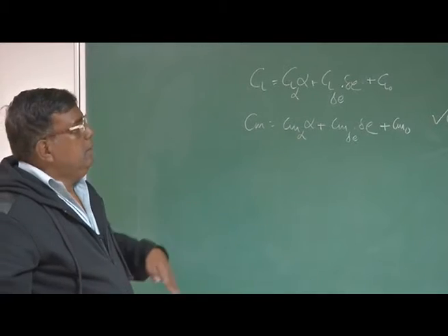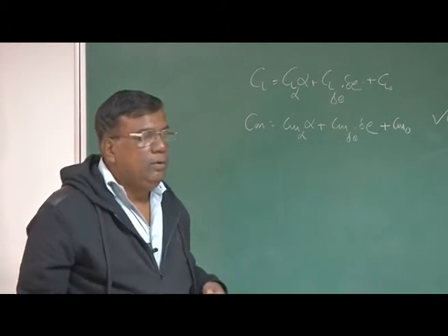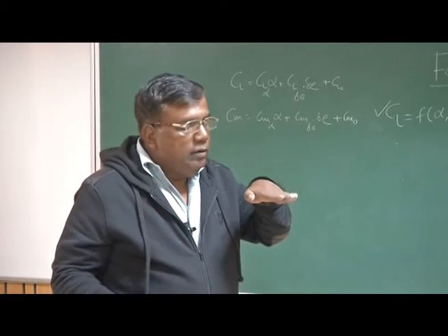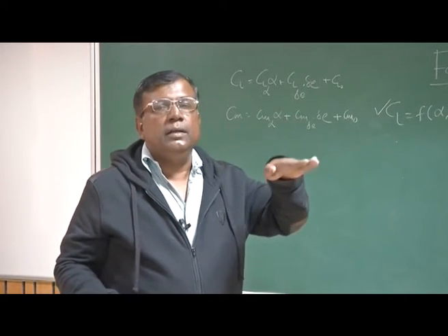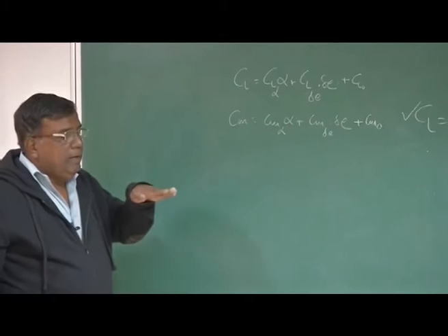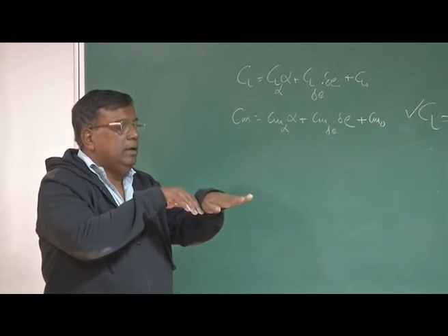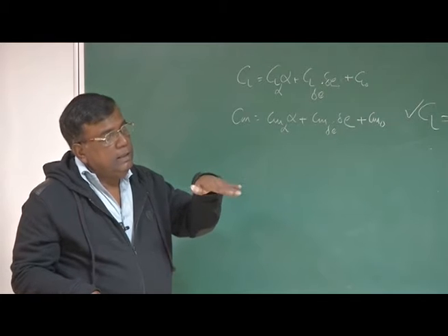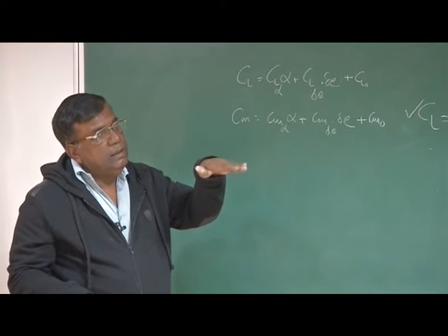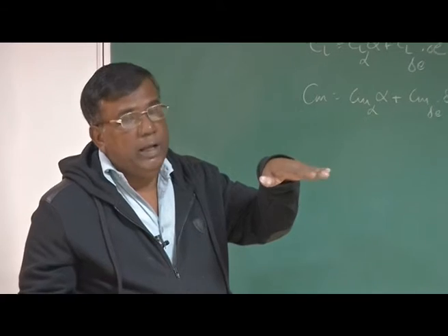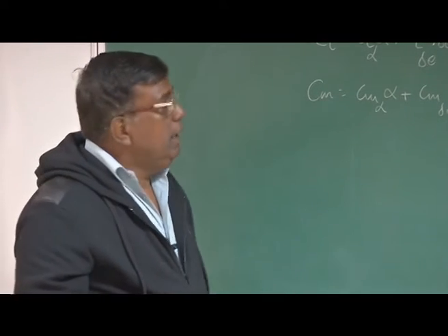But when I am writing the equation of motion for the whole airplane, and I give a delta E, actually the airplane will have some transient, then it will go to the steady state. So what happens if an aircraft is disturbed by giving an elevator? It starts oscillating in this direction. There is pitch up, pitch down, pitch up, pitch down, or it's oscillation about the y-axis.